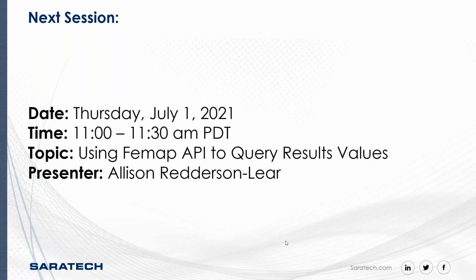The first one is, if the pattern changes, will the resulting CNC code also change correctly? Yes, it'll change correctly, but you'll have to repost it. It's fully associative, but you do have to repost the code.